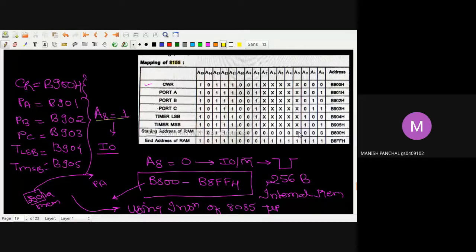वो आपके मेमोरी और साथ में आपके पोर्ट एड्रेसेस जो हैं, ऑल दे विल कम इनटू द 16 बिट्स। सो ऑब्वियसली 16 बिट्स का मतलब ये होता है कि दैट यू आर यूजिंग दैट चिप इन अ मेमोरी मैप्ड मोड। Earlier we have seen that the port is having the address of 8 bit, but here the port is having a 16 bit address. For example, if I take this control register as equivalent to one port, I am not getting an 8 bit address, I am getting the address of 16 bit. So all these ports are normally called a memory map.